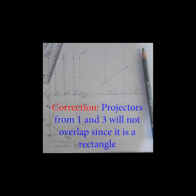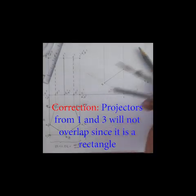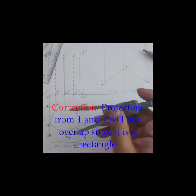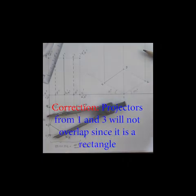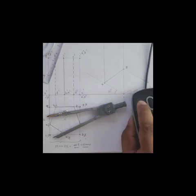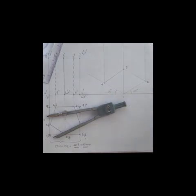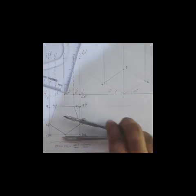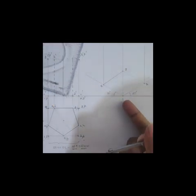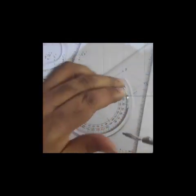And after that you have to mark the top points, and for this prism the total height is 60 mm. So take 60 multiplied by the corresponding isometric factor, 0.816, and that will give 49 mm. Take 49 mm in your compass.